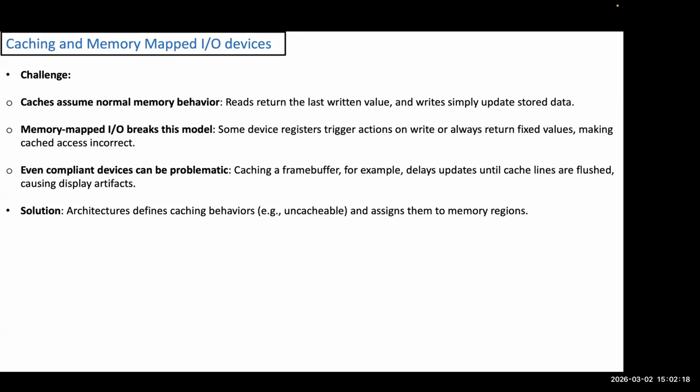For example, if you write some particular bits in the data direction register of a port, you are not only writing data into the direction register, but you are also configuring it, so it takes effect. For example, it configures the direction of the port as an input port or output port, right? So this is not the same as the behavior of a passive memory device.